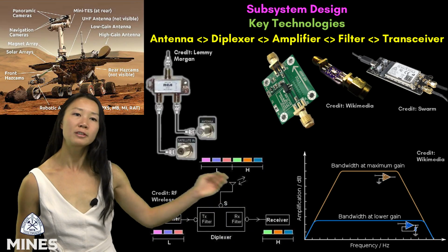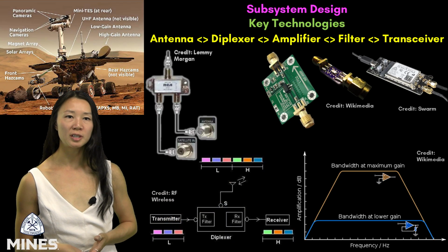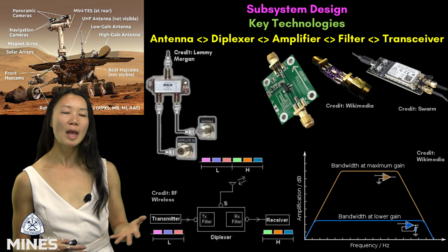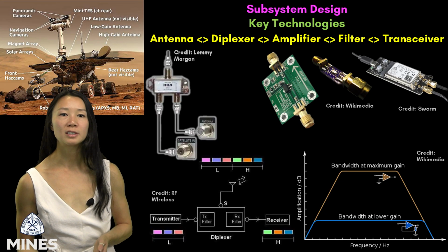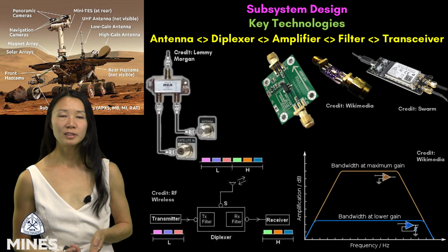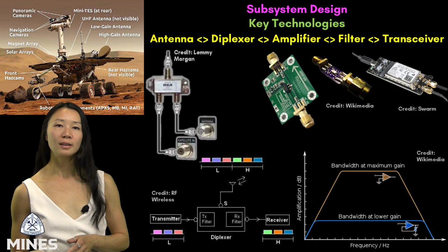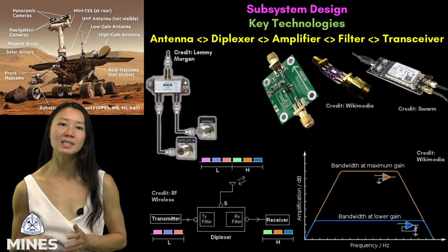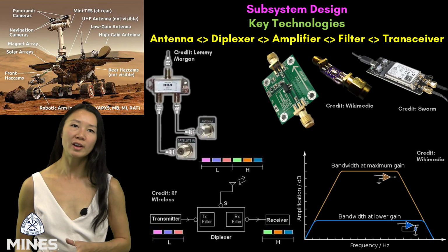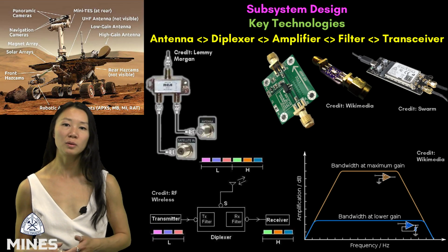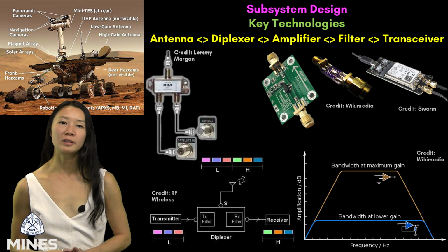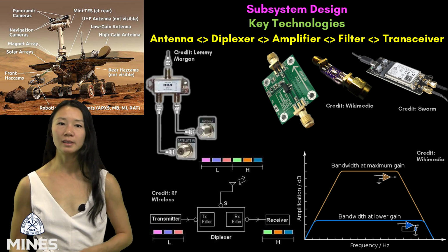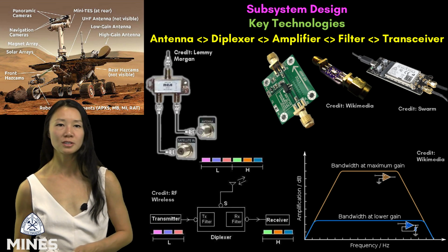This bottom graph shows this relationship, that as you increase the amplification or gain, the usable bandwidth of the amplifier often decreases. Conversely, by adding negative feedback, you can limit the maximum gain but significantly improve the amplifier's frequency response, giving you a wider, flatter bandwidth. This trade-off is critical for ensuring our signals are amplified effectively across their entire frequency range.